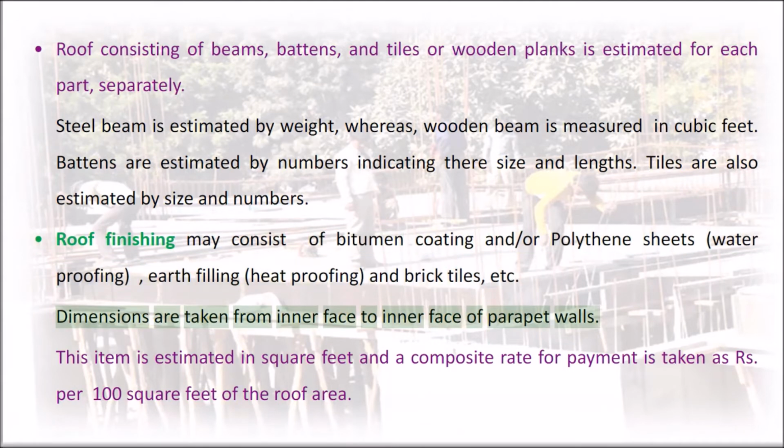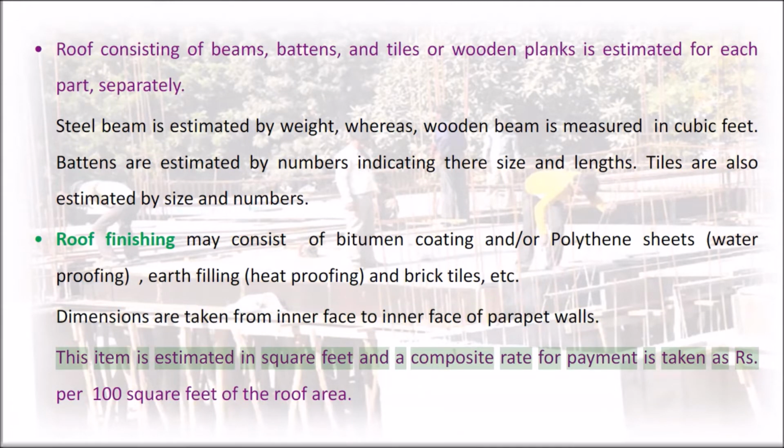Dimensions are taken from inner face to inner face of parapet walls. This item is estimated in square feet and a composite rate for payment is taken as Rs per 100 square feet of the roof area.